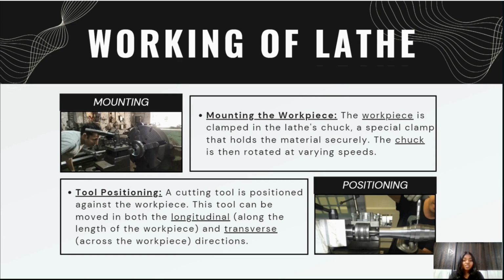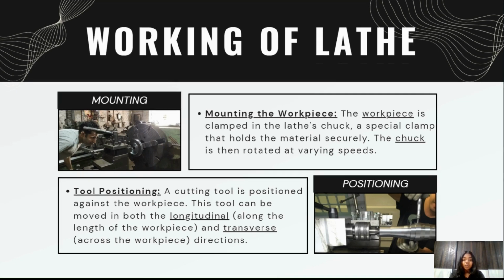The chuck is then rotated at varying speeds. The second step is tool positioning. A cutting tool is positioned against the workpiece. This tool can be moved both in the longitudinal and transverse direction.